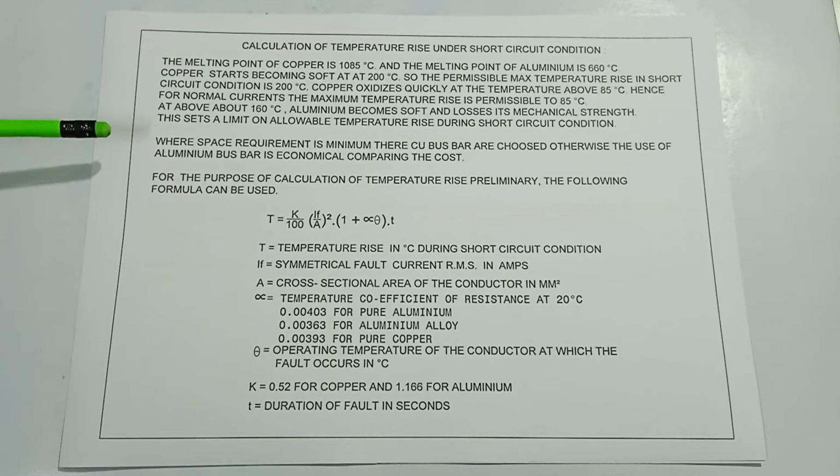Where space requirement is minimum, there copper busbars are chosen. Otherwise, the use of aluminium busbar is economical comparing the cost.